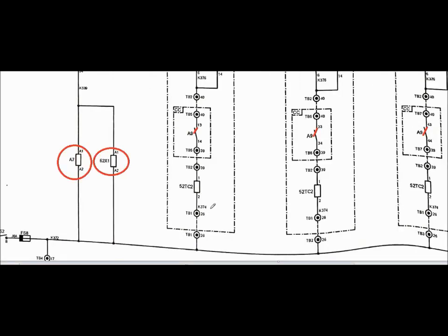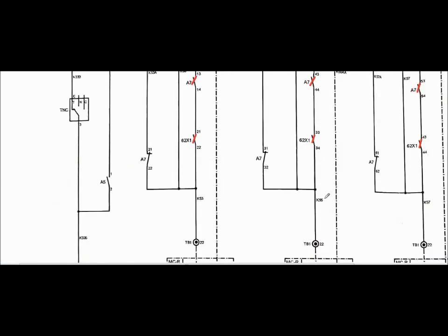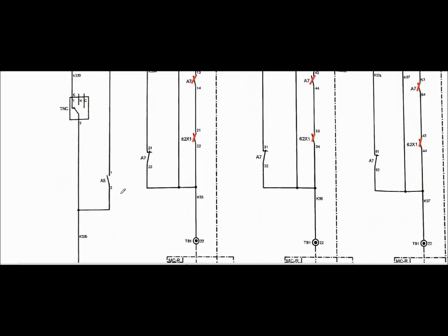Now as the red phase trip coil has tripped, there is a mismatch of the pole. As there is a mismatch of the pole, the pole discrepancy relay will be energized. A5 is the pole discrepancy relay contact. After the time of 1.5 to 2 seconds, which has been set in the timer of the pole discrepancy relay, the auxiliary contact comes to NC position.